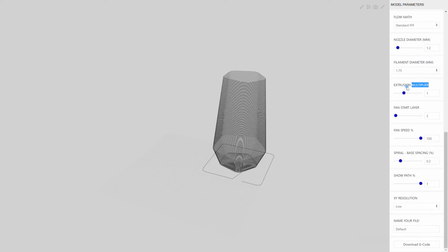And once you do this, the slicing module will deal with these parameters in the computation. It will also take into account, of course, the height of the layer and the length of the extrusion, and will automatically calculate the correct value. If you're using clay or pellets, unless you already worked out a profile with this value, a better solution could be that of using the multiplier only.